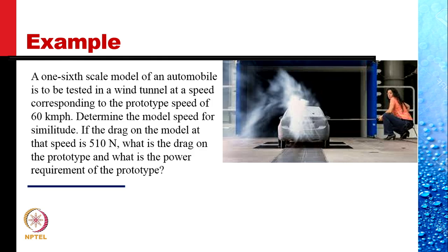So as before, we decide on what are the important forces, and we realize that in this model, where there are no free surfaces involved and where there is no characteristic pressure difference, the only forces that need to be modeled are inertial and viscous forces.